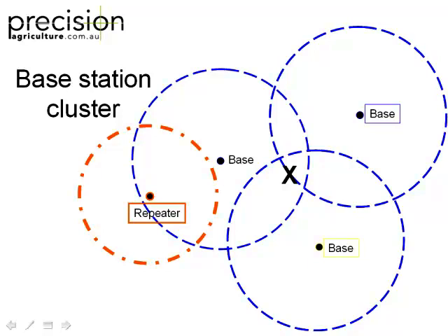If you set up your AB lines based on this base station in the middle here, and then you went to one of these other base stations, your lines could be 2 or 3 metres out, because those stations only average their location for, say, 60 seconds to get a rough average of where they are, and then they work off the distance between you and the tractor.